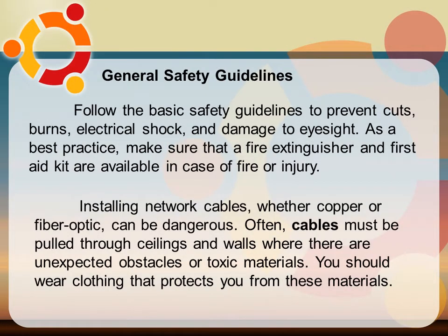General safety guidelines. So you need to follow the basic safety guidelines to prevent cuts, burns, electrical shock, and damage to eyesight. As a best practice, make sure that a fire extinguisher and first aid kit are available in case of fire or injury. Installing network cables, whether copper or fiber optic, can be dangerous. Often cables must be pulled through ceilings and walls where there are unexpected obstacles or toxic materials. You should wear clothing that protects you from these materials.